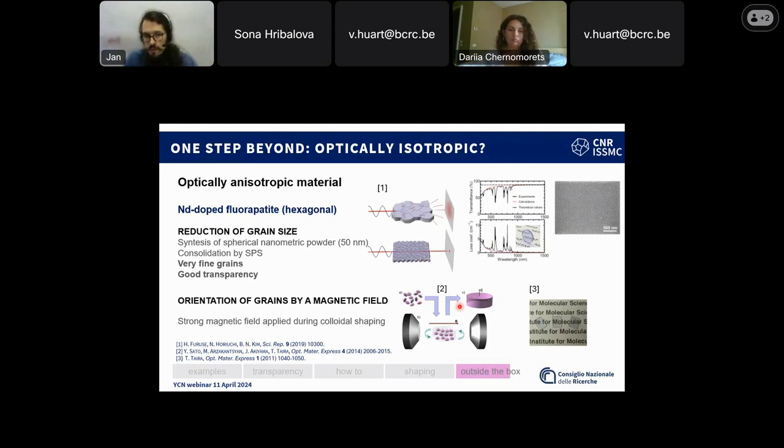And some results. This sample is characterized by quite high in-line transmittance, which is above 78% at 1100 nanometers, while for this material at this wavelength, the maximum is 82.4%. So this result is quite close to theoretical, while the second one is completely opaque.